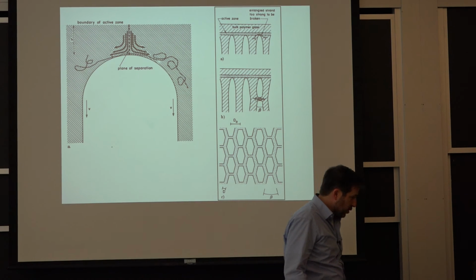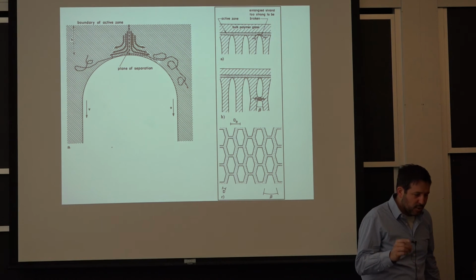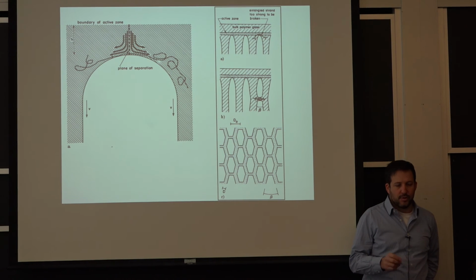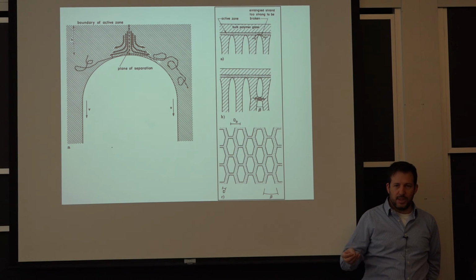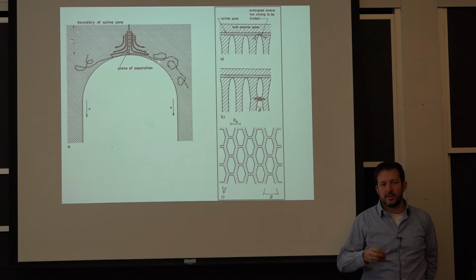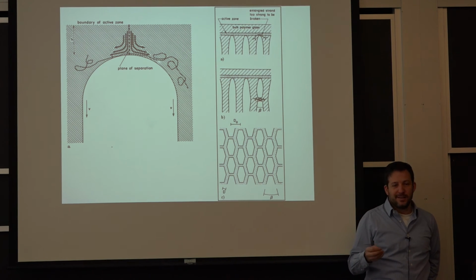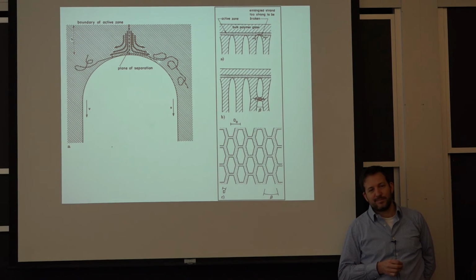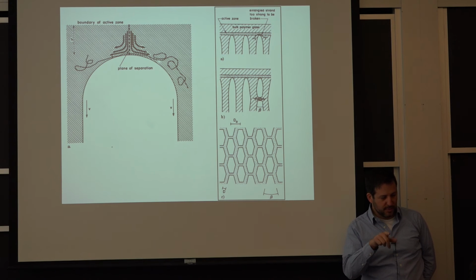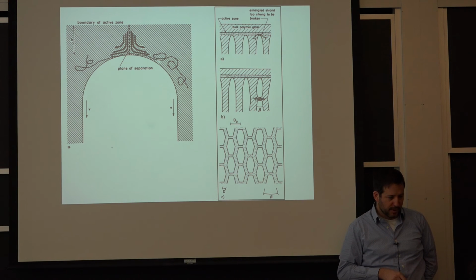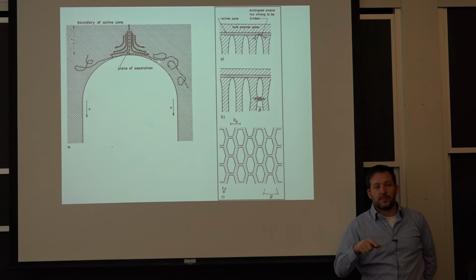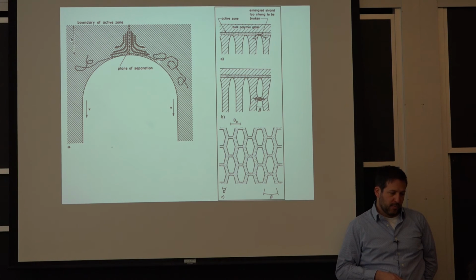In terms of crack resistance, the main driver for a slow crack to continue in a polymer, or a craze to grow and eventually break, is the molecular weight.